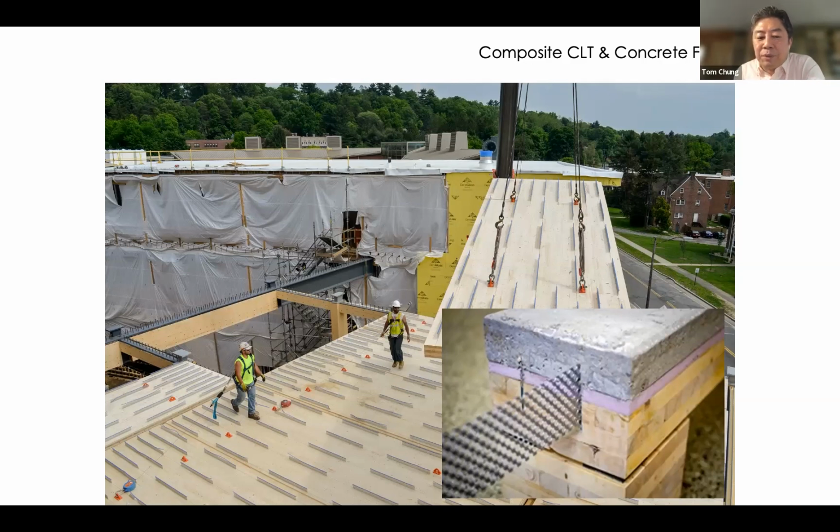In this case, what we used was a composite technology, which was researched in part by the professors at the university, in which a perforated metal connector was installed, and you can see those fins sticking out of the CLT panels. That allowed, when the concrete was poured on top with a layer of acoustic insulation in between, for the concrete and the CLT to be mechanically fastened together